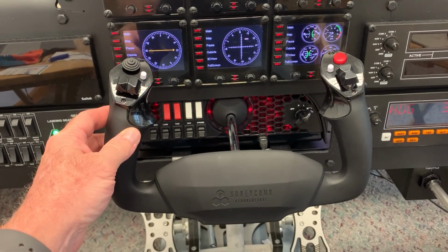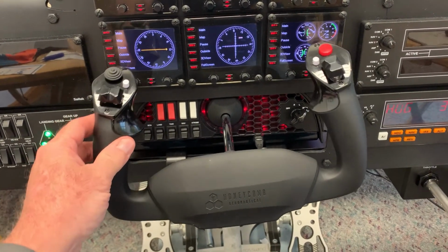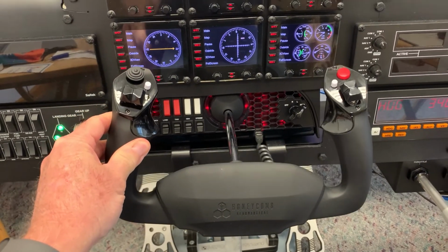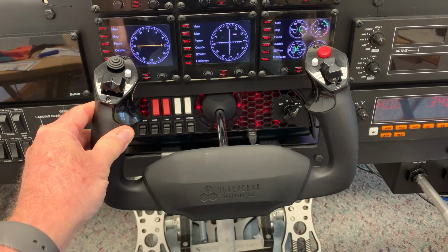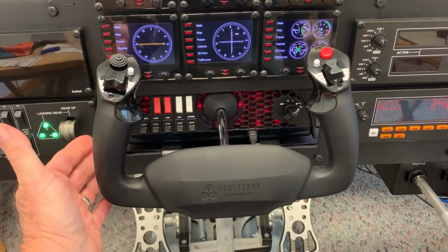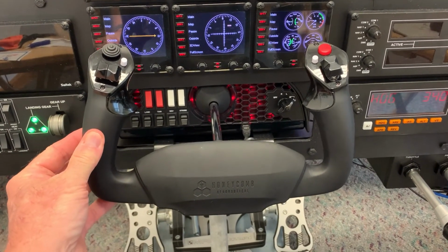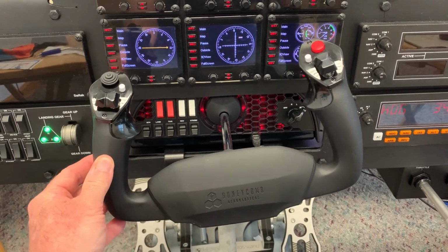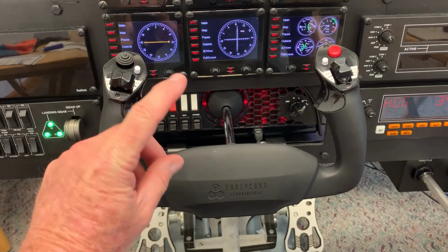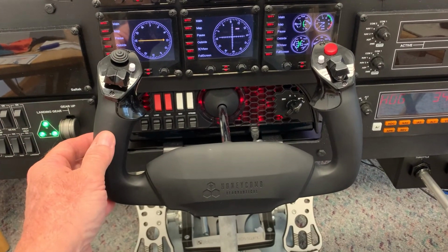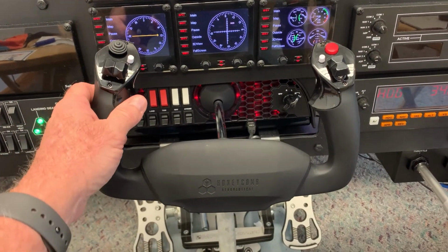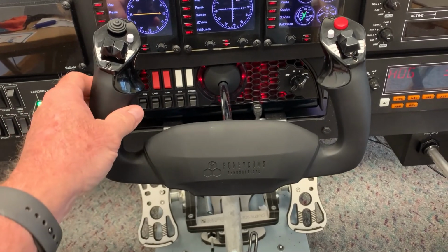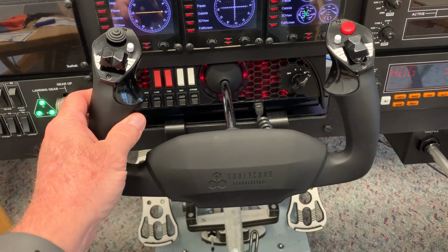The yoke controls both ailerons by turning it side to side and the elevator by pushing it forward and pulling back. I cannot stress enough how important it is to handle the yoke gently. Fast, abrupt movements can cause your aircraft to depart controlled flight and cause damage to the expensive hardware. It's human nature when something goes wrong, you want to make drastic adjustments to compensate for the problem, but in reality, you're just making the situation worse.